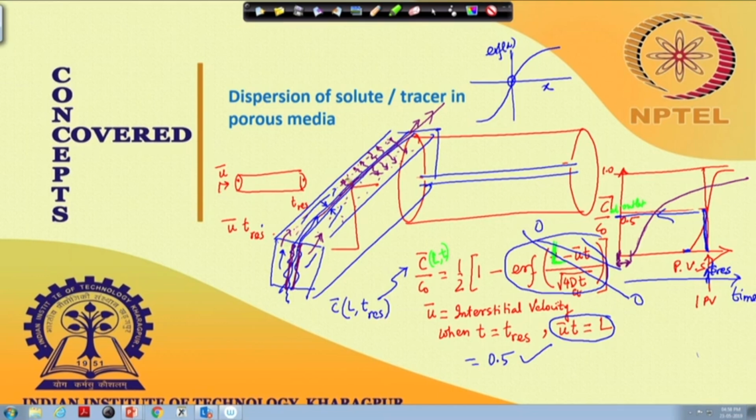Always there would be some minimal flow that will take place through this side very slowly. But the main flow would be through these cracks, and as the solute travels through them, it will continuously be diffusing into the adjoining pore space, which is filled with liquid of 0 concentration. Because of this diffusion, there would be dilution of the front. So, it would be much less than 1.0, and one has to continue to flow.